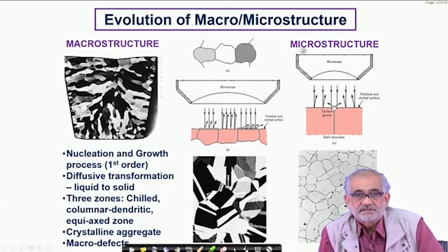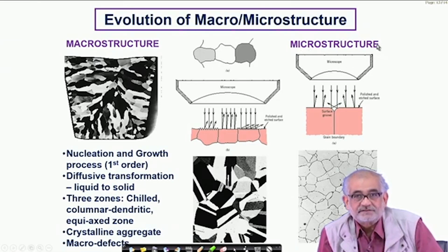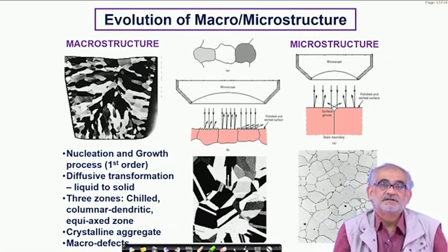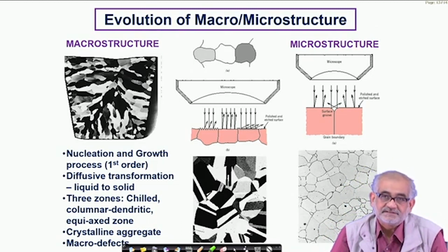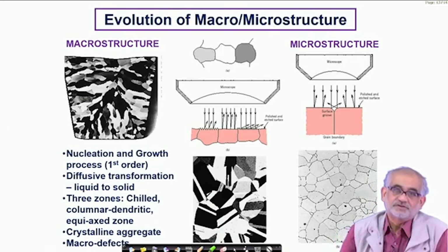So all these properties, most of the engineers would tend to believe that they are one and the same for the solid so long as the composition is the same. But the metallurgists and the materials engineers understand the worth of microstructure, which actually is, as I said, a composite or a complex body of knowledge comprising the shape, size, identity, volume fraction, orientation and distribution of the various phases that make up the solid.